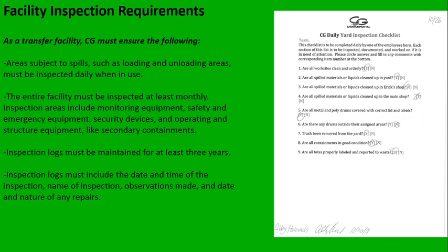So the entire facility has to be inspected at least monthly. I have you guys inspect the yard weekly. And we just recently redid those inspection sheets so they're a little bit more thorough. We have to maintain these logs for at least 3 years. The logs have to have the date and time of the inspection, name of the inspector, observations made, and date and nature of any repairs.